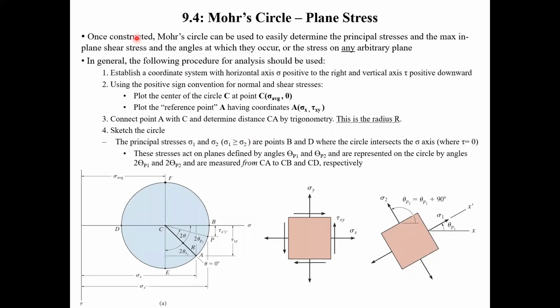So, once your Mohr circle is constructed, you can use it to easily determine your principal stresses and the max in-plane shear stress and the angles at which they occur, or the stress on any arbitrary plane.